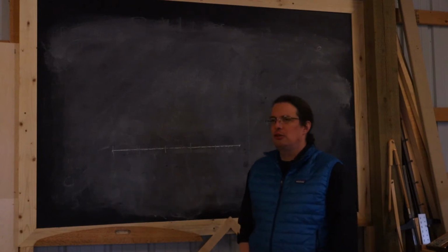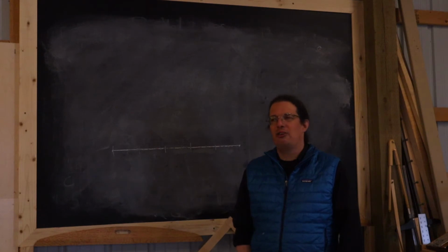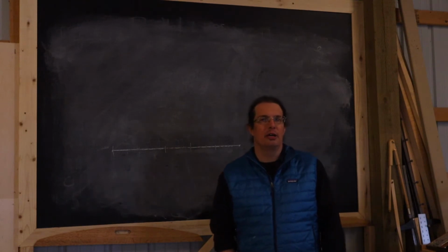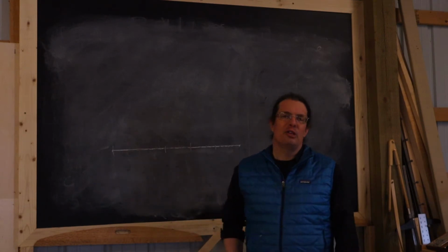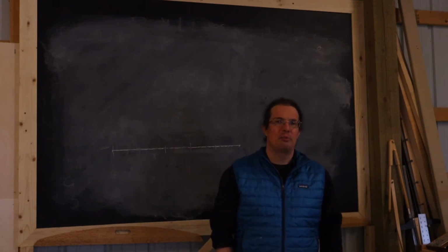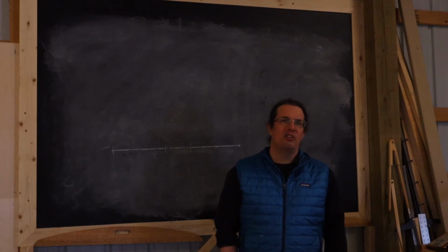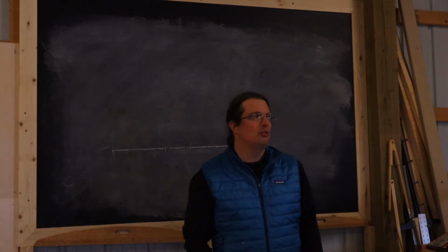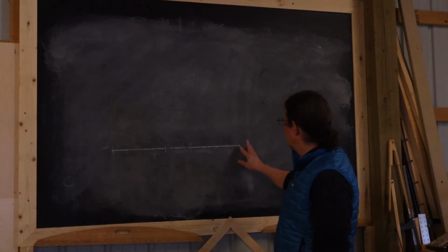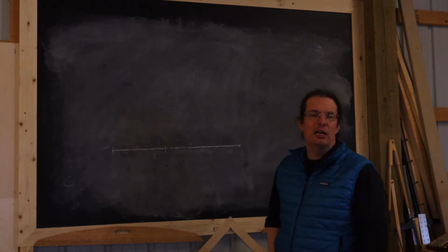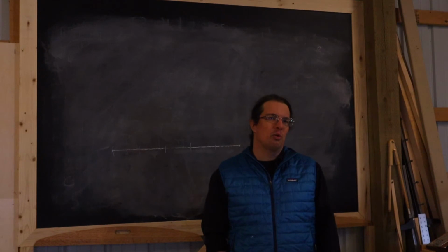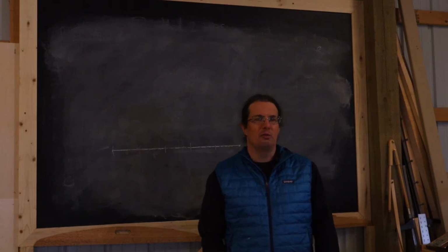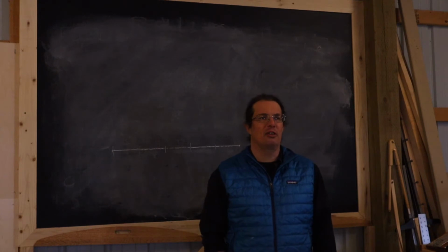Where this technique doesn't always work so well is, imagine that you were trying to divide a line up into 29 or 101 or 113 equal segments. Those are going to be very small steps. It's going to be difficult to set your compass to those step sizes. And small adjustments of your compass are going to lead to large errors in the end, once you're stepping towards the end of the line segment, because they compound with each step. So this technique works relatively well for a relatively small number of subdivisions, something like a set of single digits.